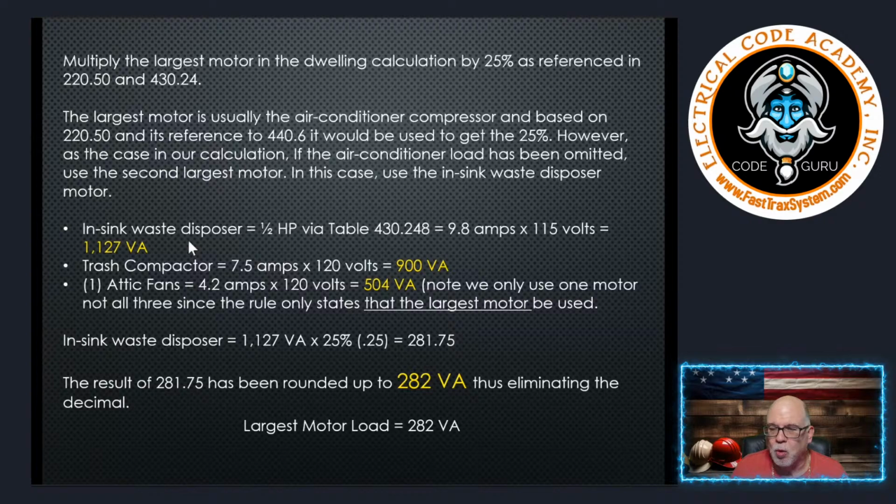And again, people say, well, why did we not use the AC? Because that is the largest motor, but we discounted that entire load when we did AC versus heat. So it's gone. That's why we're hunting for the next largest motor, and that's the waste disposal. That makes sense, I hope. If you don't believe me, you have to have a leap of faith here. That is exactly how it works. I've been teaching this for 38 years. So we need to add that as the largest motor. I'm going to write this down here, and it's 282.